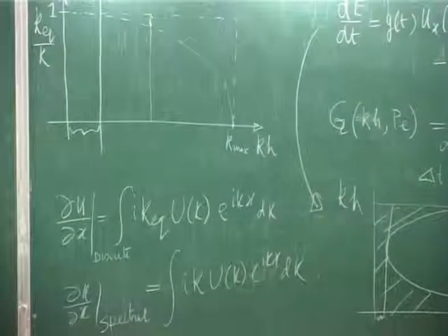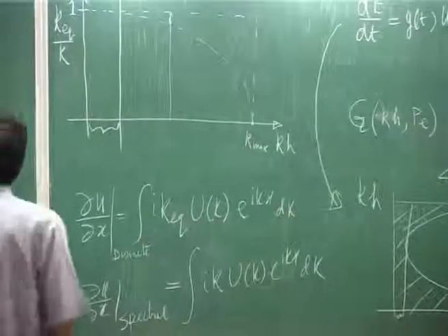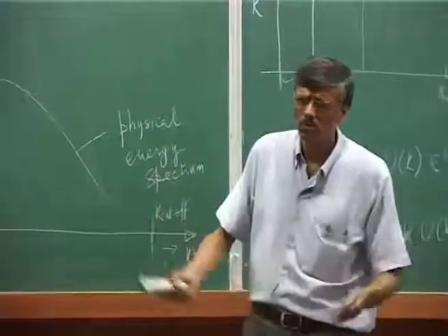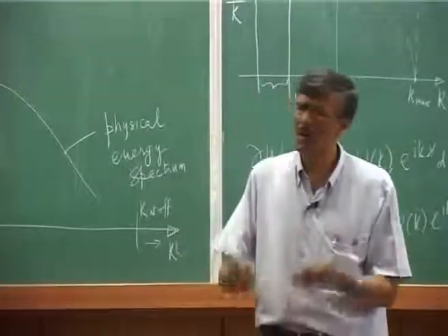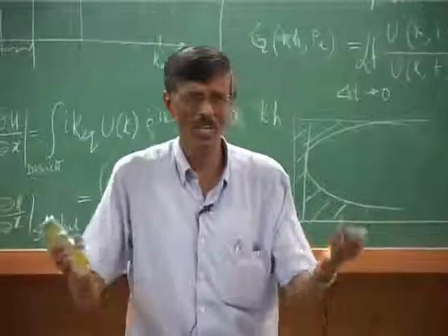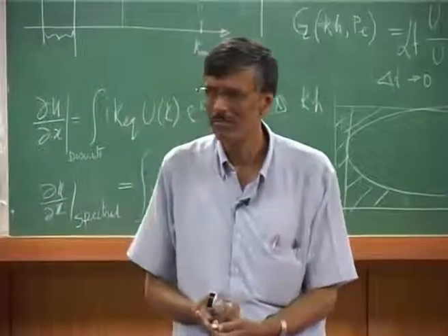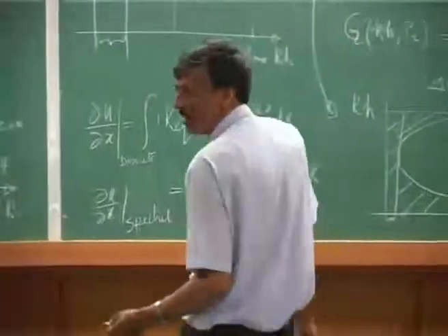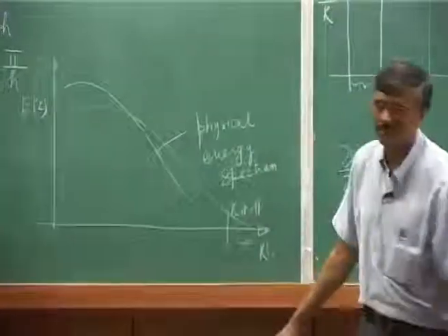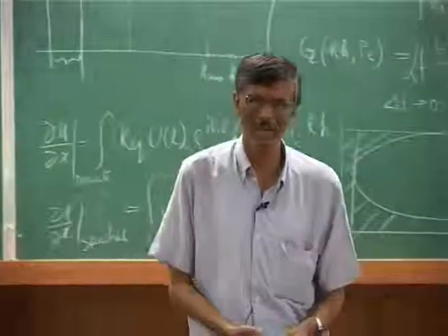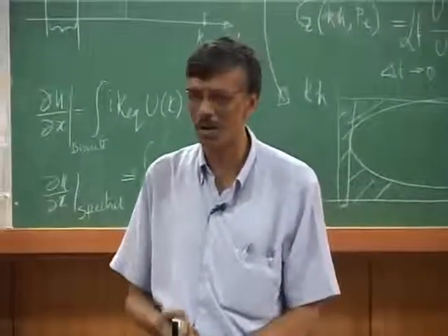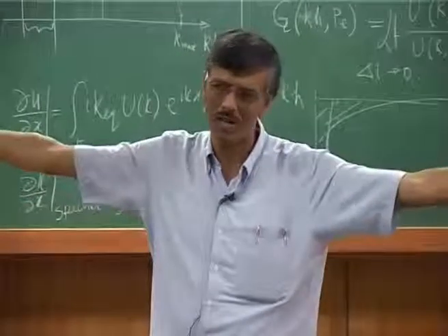So, I suppose this is what I told you about water flowing in a pipe, for a particular velocity, for a particular flow rate. The moment I change the flow rate, my spectrum may change. I could get something like this, right. Those of you who are familiar would know there is something called Reynolds number. If you increase the Reynolds number, your spectrum becomes wider.